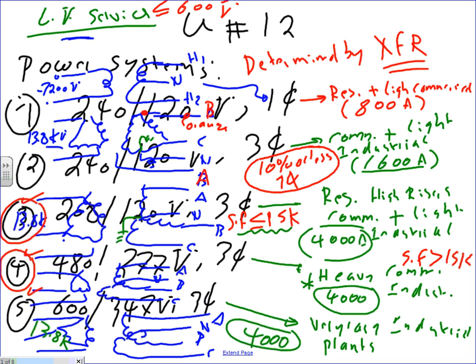That's what I always thought of as low voltage. I call them low voltage services because the secondary side that you're looking at right here is all low voltage. Any questions, guys, about the low voltage services? So any building that you walk in, Phil, it's either going to be 208/120 or 480/277. You might encounter from time to time 600/347 volt buildings, but not a whole lot. The same thing with number 2, it's rarely used. And number 1, of course, is residential, mostly residential and light commercial.